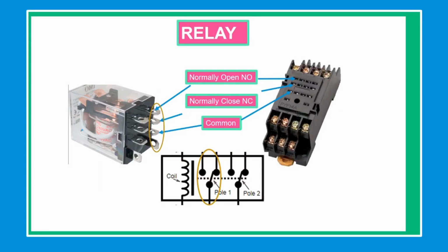A relay can be used to control several circuits by just one signal. A relay contact has one or more poles, and each contact energizes one circuit or stops another circuit. Protective relays can prevent equipment damage by detecting electrical faults like overcurrent, undercurrent, overloads, and reverse current. Additionally, relays are also widely used in heating equipment, pilot lights, and audible alarms.